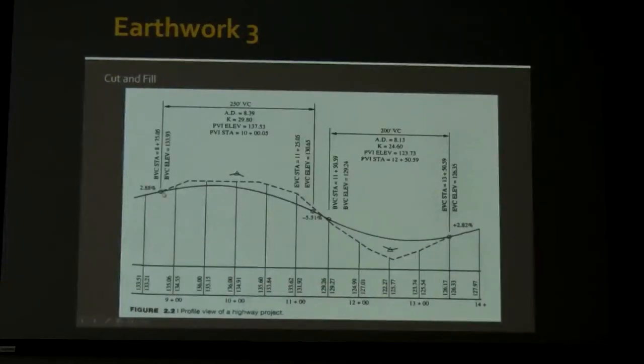Beginning at station 75.05, we will look at that there's a 2.88% slope there. What we want to do is smooth this out so that we can have a smoother roadway with appropriate sight distances for stopping and for passing. Here the existing grade is a little bit rugged, and we're going to do something about that.